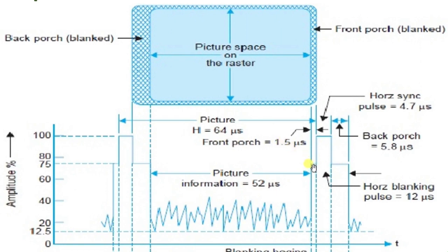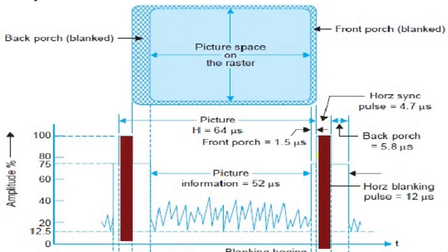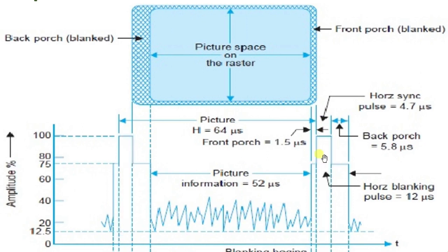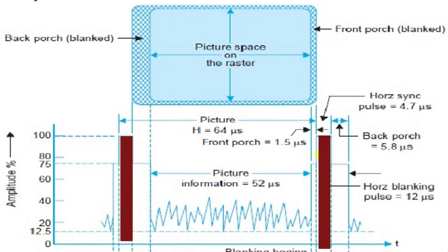Now subtract the flyback time of 7 microseconds. 8.93 minus 7.00 equals 2.93 microseconds. 2.93 microseconds is the blanking time still remaining after the retrace to the left periphery has been completed. Even though the blanking is still in progress, the sawtooth deflection waveform causes the scanning beam to begin tracing along the line. As a result, the first part of the trace on the left is left blank.